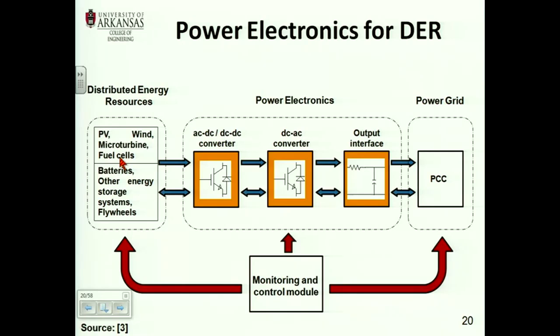So we are talking about a different type of technology. The inverter cannot conduct that current for more than 10 microseconds. So what you do is you sense the voltage drop across the switch, and when it exceeds 3-4 volts, you interrupt the triggering signals. That's what you normally do. Why am I saying this? Because as you go and work, you are going to hear a lot that distributed generation increases the fault current. And the answer is, it depends.